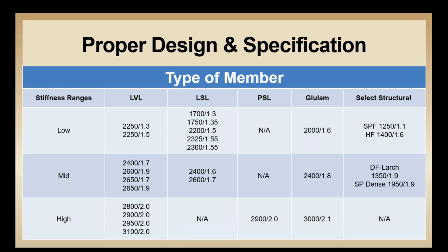Comparison with some commonly specified sawn lumber grades shows how these products compare with these grades and how glulam or SCL could be substituted for similarly sized specified sawn lumber products. But keep in mind that while this type of substitution is technically acceptable, the member design for the actual conditions using product-specific tables or software could result in a more economical option.